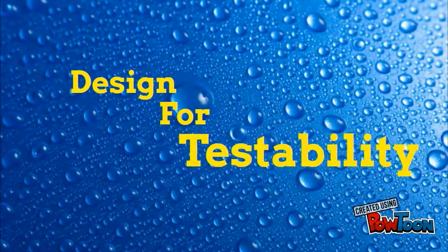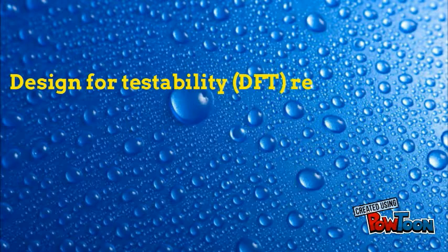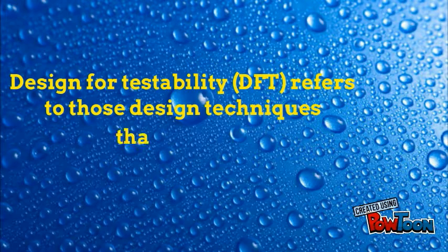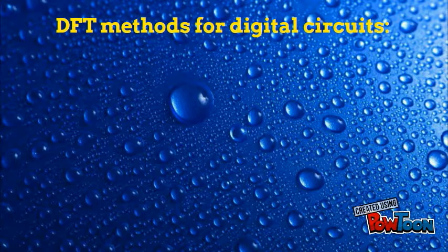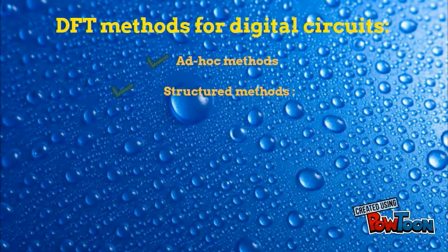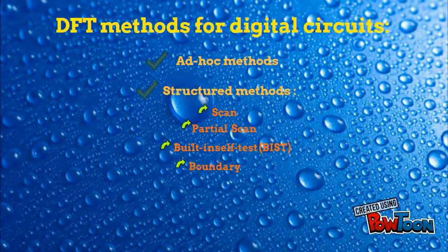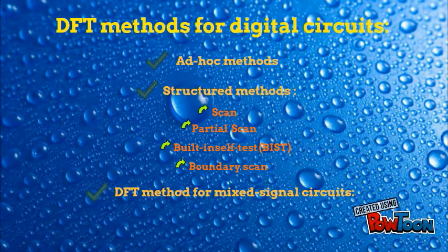Design for testability. Design for testability, or DFT, refers to those design techniques that make test generation and test application cost-effective. DFT methods for digital circuits are ad hoc methods and structured methods: scan, partial scan, built-in self-test, and boundary scan. For DFT methods for mixed-signal circuits, the method is the analog test bus.